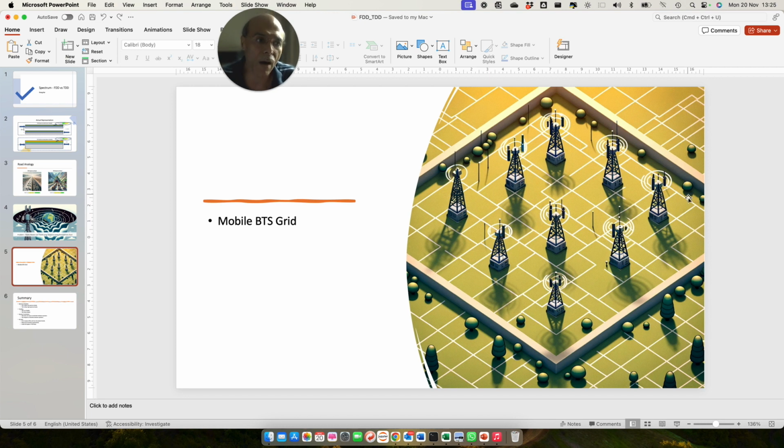So you have to block this base station's receiver, right? Even though this particular base station has transmitted for 20 milliseconds, you have to extend the time for another, let's say, 3 milliseconds or 4 milliseconds, depending upon the time the signals are already in the air. So as to prevent those signals getting into the receiver, you have to lock that particular time. You can't do anything within that time period where the signal is already in the air.